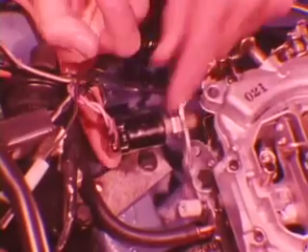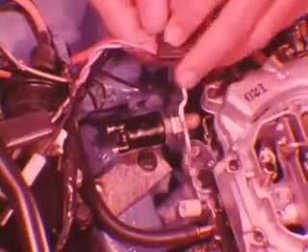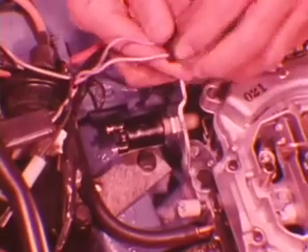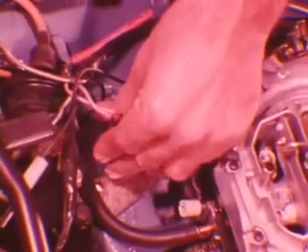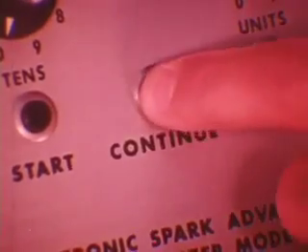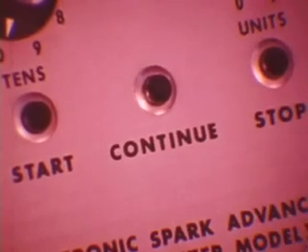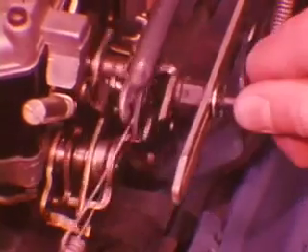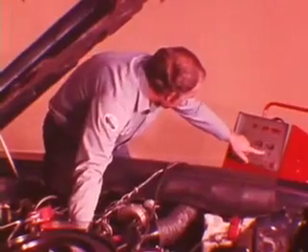The connector may be disconnected and reconnected as you make the adjustment without disturbing the test sequence. After the code 8 adjustment, you do not have to go back to step 1. Just press the continue switch, and if the adjustment is correct, you will now get code 7. Your instructions for code 7 are to hold the throttle wide open as you press the continue switch. You should now get code 10, since code 9 is not used.